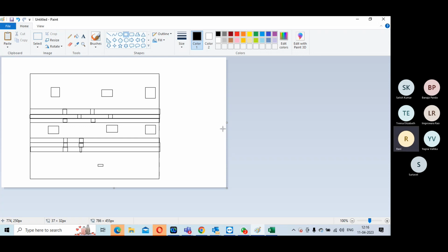That's why I told you the golden rule. Data flow diagram. If the data flow diagram is not available, use the hierarchical browser. Sit with the designer, because that is the only window you have to actually interact. You cannot do it close to tape out and say I want to talk to the designer, my timing is not working. Floor plan only, we need to spend time.